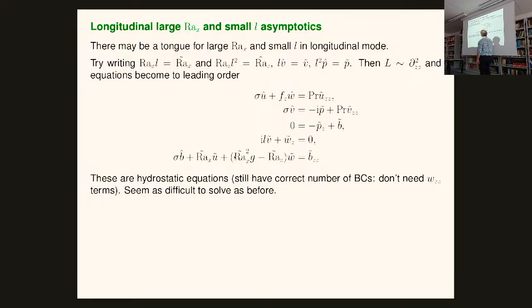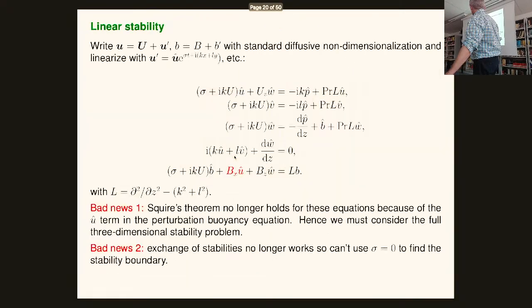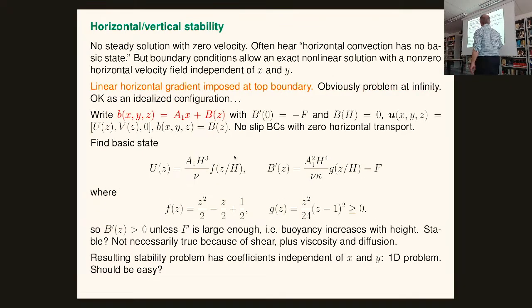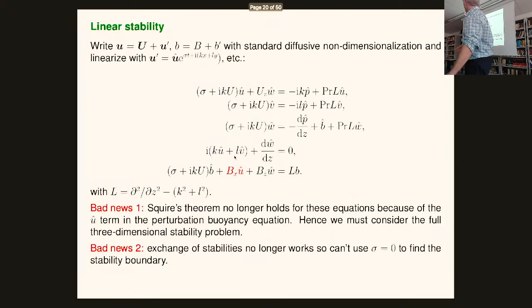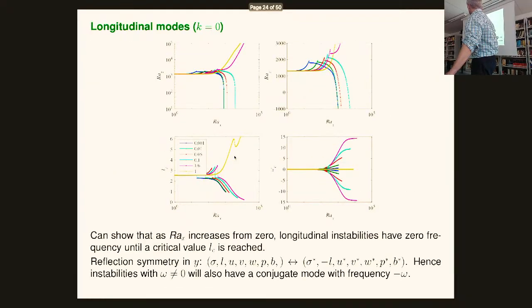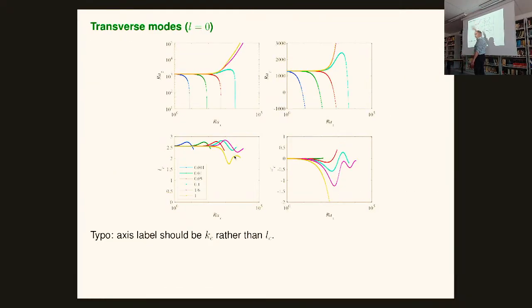What you also see is that in this non-dimensional version, and I should have shown it before, clearly there's, in the W term, which is the buoyancy gradient in the vertical, a vertical Rayleigh number and a horizontal Rayleigh number squared. So that was implicit in my initial discussion of the equations. Where was it? Here we go. This is A1, which is Rayleigh sub x, A1 squared, this is Rayleigh z. So you expect that there's some balance between Rayleigh x squared and Rayleigh z. And that, in fact, is the scaling at the top. That curve going up is exactly that scaling that you expect.